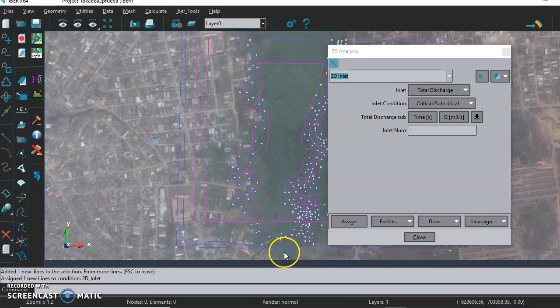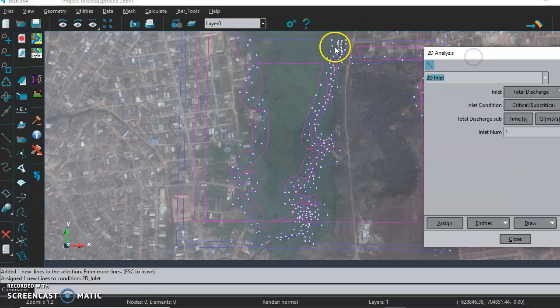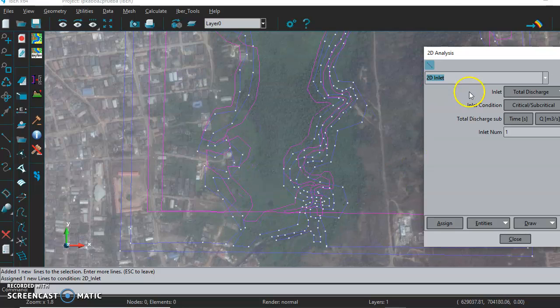Okay. Later, what we have to do? Okay, to run a water flow here in the river, we need to create an outlet to say to the program where the water flow comes and where the water flow goes. We will create the outlet regardless of the fluid that we think will be here or here.